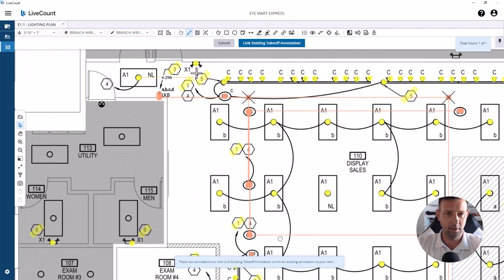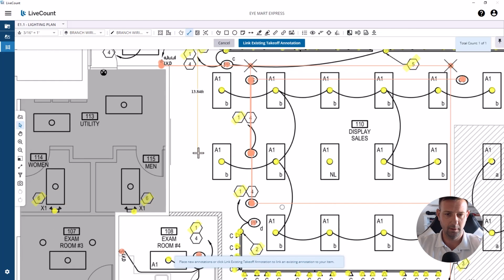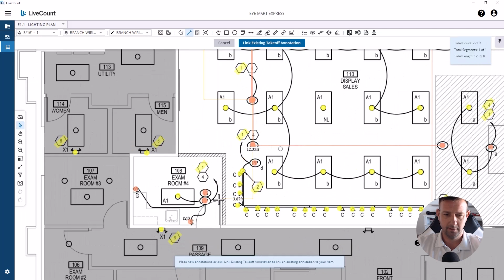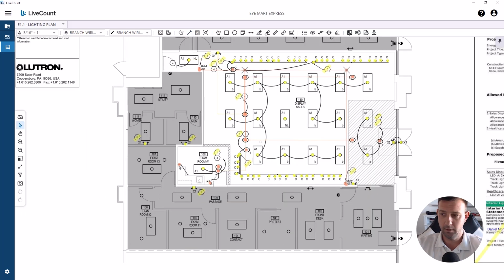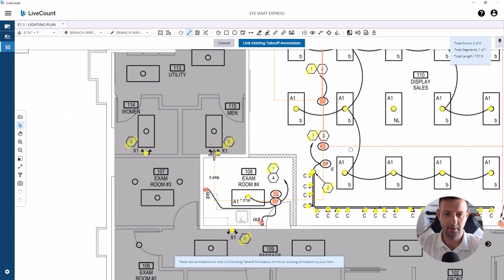And I'm just going to run everything out, all the power. So hit all the locations where I need constant power. That means all the emergency fixtures. That means the lighting controls, controller, and then the power packs are switch legged. So it looks like we got to hit a power pack right here in the exam room. So we'll go boom. We'll go to this lighting controller. We need constant power there for that circuit. We need constant power at this power pack for power, and then I'm just going to tie all these together, all the emergency fixtures they're adding.